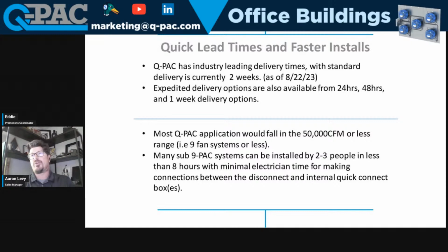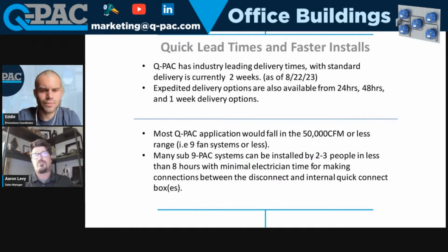A lot of questions people ask about EC fans is what their lifespans are. They have SKF bearings. Their L10s are typically between 50 and 80,000 hours. So they'll have about 10% field failure rates somewhere between 5.5 and 10 years. Their mean time between failure is somewhere around 100,000+ hours. We give you a 5-year warranty, and even the 10% field failure rates tend to be after that 5-year warranty.